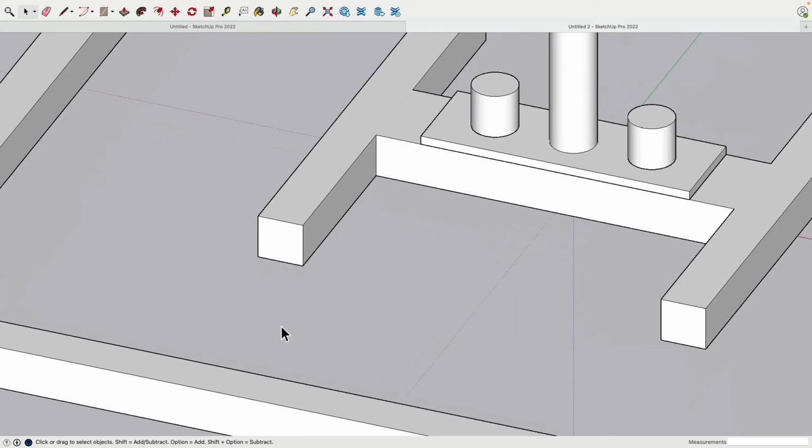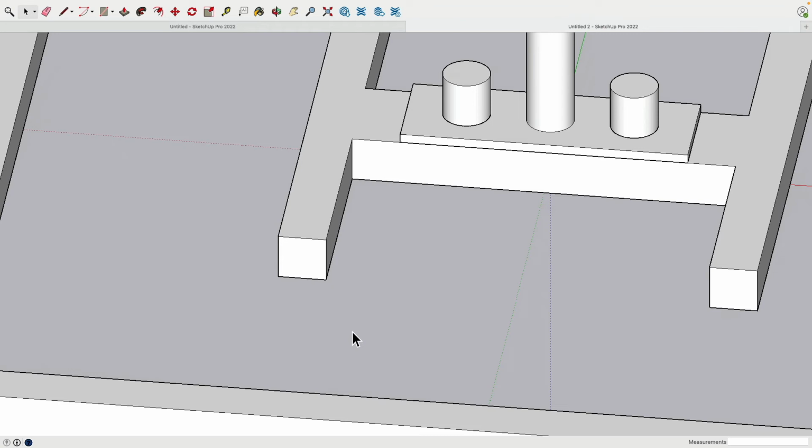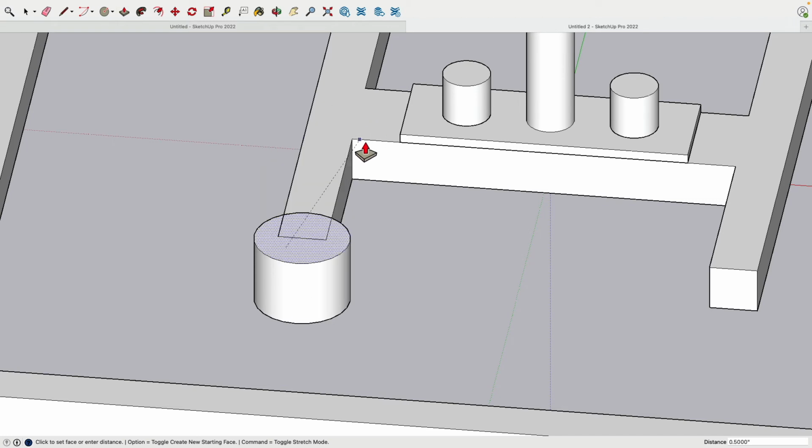So actually everything is done besides our luminaires. So we're going to, again, just remodel this in a more simplified way. Taking basic dimensions of objects and then trying to rebuild it with cubes, cylinders, and basic shapes, if possible, very often works out when we have a certain quantity of objects. That's really key, quantity. So I do a circle, arrow up. So it's drawn on the ground plane, and this will be 0.5. This circle goes down, extruded 0.25. Then it goes up to this edge and another 0.25 to the top.